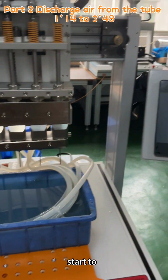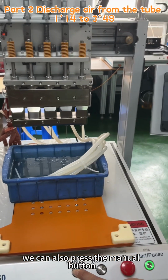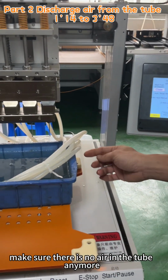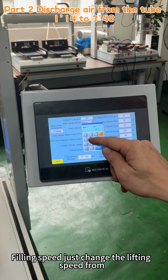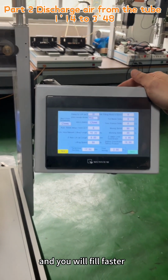Then you start to discharge the air from the tube. We can also press the manual button. Make sure there is no air in the tube anymore. If we want to change the filling speed, just change the lifting speed from 30% to 50%, and you will fill faster.